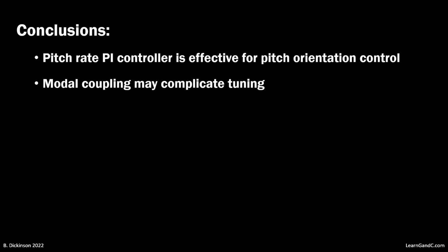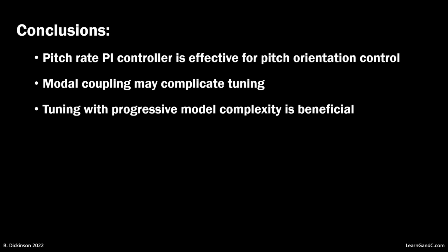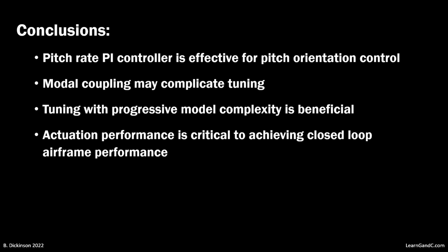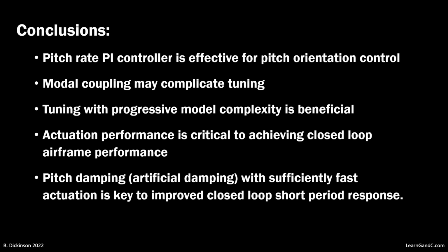In this, we saw how modal coupling can complicate tuning, and this led to the idea of starting simple, with the essential dynamics to be controlled analyzed first, and this would help us isolate cause and effect. We also showed how actuation performance can be critical to achieving closed-loop airframe response, and that adequate pitch damping combined with faster actuation was key to providing an airframe fast and damped short period response through integral gain tuning.